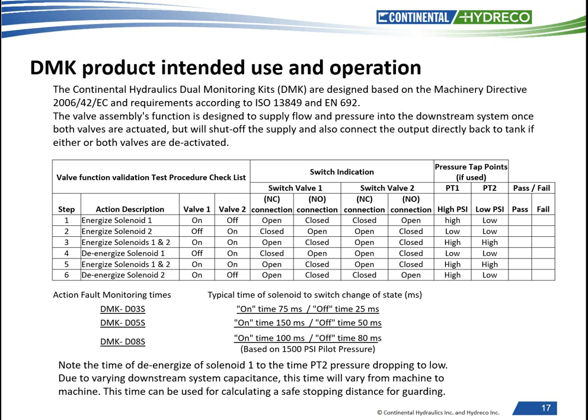There are two very important times that must be noted. Besides the valve performance response time, we also need to know the hydraulic system response time. The overall system response time is very key. System response time refers to the amount of time from when a valve is shut down to the time that the outlet flow and pressure have dropped to a safe or zero output. In this example, this time will be used by designers to determine the distance that mechanical guarding will need to be positioned away from the function to ensure we are kept out of harm's way.